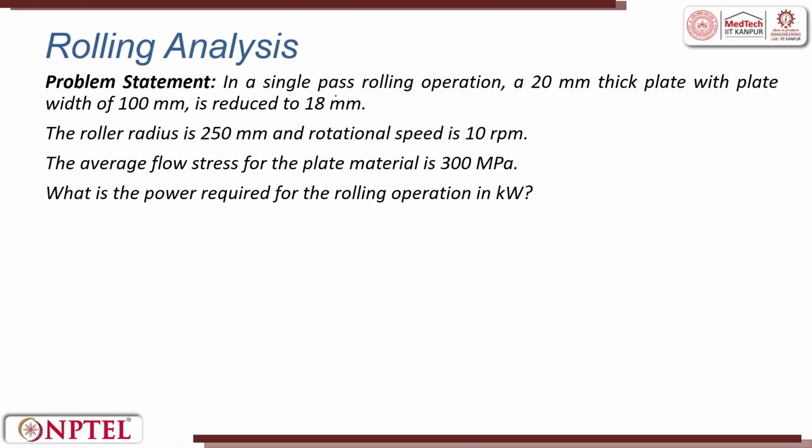Let me also now take a problem in rolling where we will try to determine the power or force that is there in rolling. In this problem, a single pass rolling operation with a 20 millimeter thick plate with plate width of 100 millimeters is reduced to 18 millimeters. The roller radius is 250 millimeter and rotational speed is 10 rpm. The average flow stress of the plate material is 300 megapascal. What is the power required for the rolling operation in kilowatts?